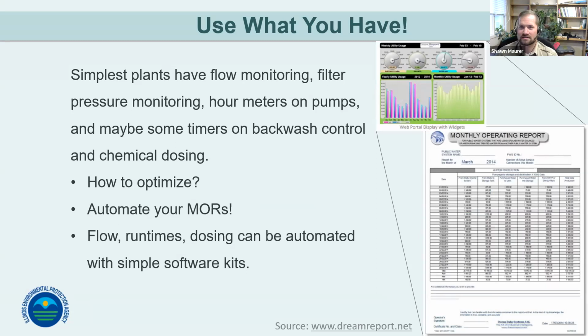One of the things you can look at is your monthly operating reports. We've seen a lot of these in doing our assessments with water facilities that are filled out by hand. When you've got the sensors in place, if you automate it a little bit, put in a SCADA control system, it could populate those reports for you with flow, with run times for pumps and motors. With a little bit more sensor control, it can also populate the chemical dosing that's going on with that system. And so that could save you a significant amount of time just in generating the reports.